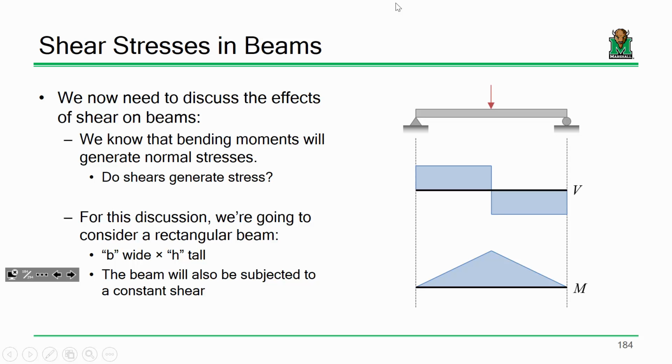He would not be happy with me because he would not be able to study for the celebration coming up. But in all seriousness, what do you think would happen to the strength of this section? Be a lot stronger, okay? Because the fact that the pages are stuck together, they are going to resist load. And think, what's happening? The pages are sliding like this. They're shearing against one another, right? So we need to consider that, because in a solid beam, that is what's happening, right?